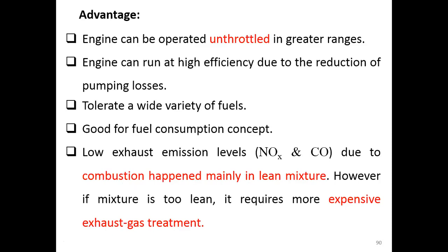The combustion of the rich mixture happens only near the spark plug, but the main combustion happens in the lean mixture for the larger portion of the cylinder. So low exhaust emission happens. Okay. However, if we provide too lean a mixture, this is the important thing.